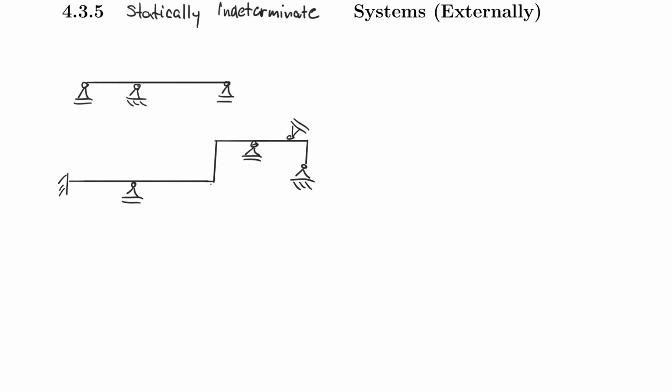And so now the one thing that you need to understand about statically indeterminate systems in this class is how many times is it statically indeterminate. So can you guess which the degree of static indeterminacy is for this system? Go ahead and do it. And after you finish pausing the video, I'll solve it for you. I have 1, 2, 3, 4, 5, 6, 7, 8. And so this is to the 5th degree, right? So 5 times statically indeterminate, so 5th degree.